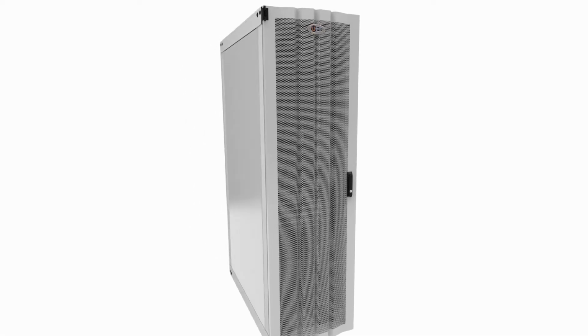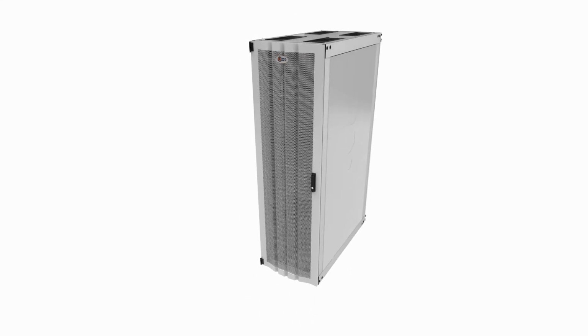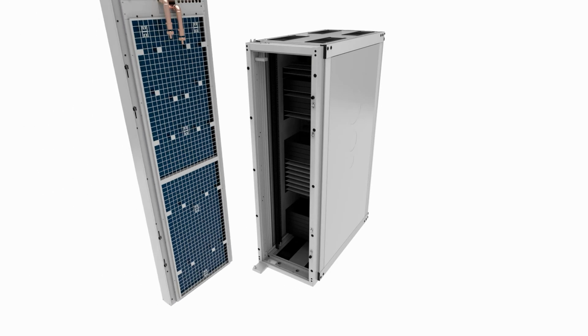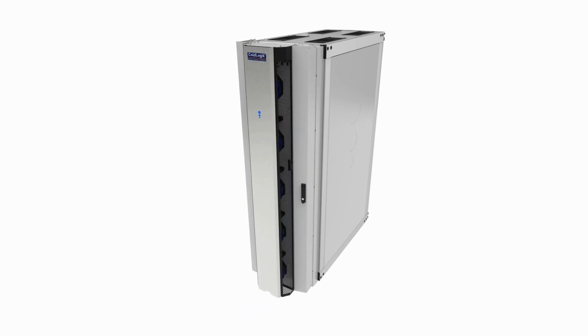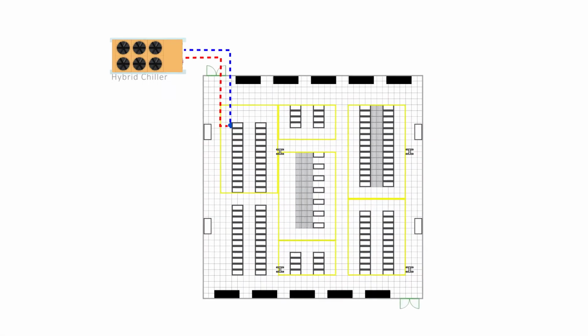Having run the flow and return pipework to the necessary racks, which could be to either the top or the bottom, the next part is to remove the existing rear door from the IT rack and replace it with a ColdLogik interface frame, which can be fitted to most OEM racks. Once fitted, the rear door cooler can then be hung and pipework connected. Simple fit. Connect and play.